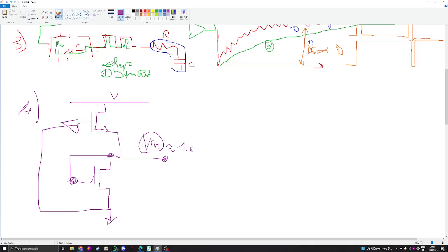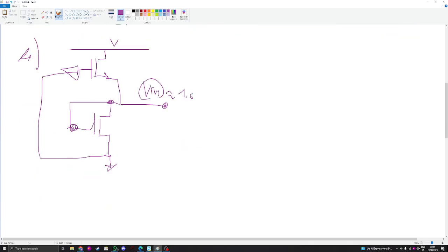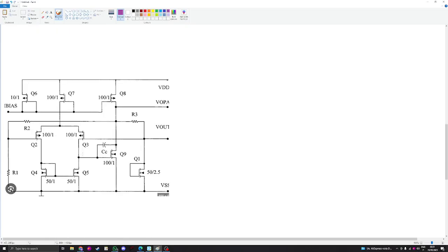So this is just the main building block of a voltage reference. The real voltage reference can look like this. You can recognize the main block, which is the saturation region of the MOSFETs. Then you can recognize the current mirror, the differential stage, and also the compensation capacitor. The powerful thing about this one is that you can use whatever configuration you need to compensate as much as possible.